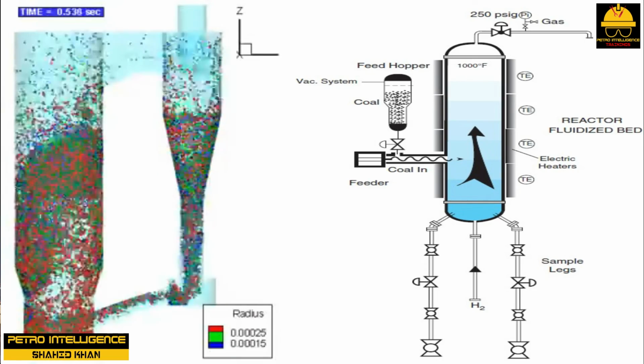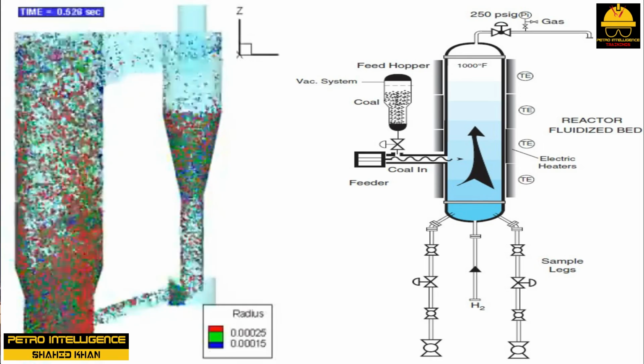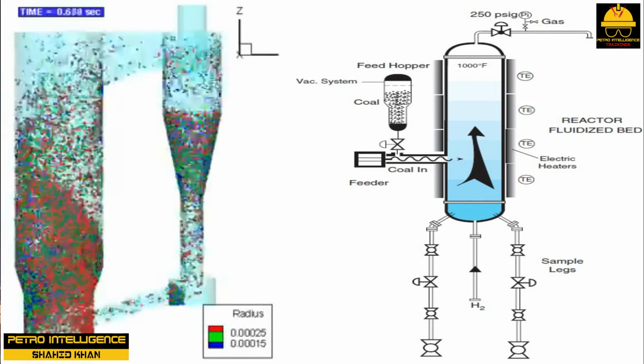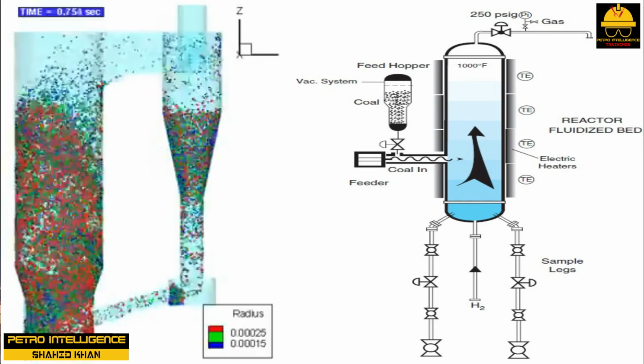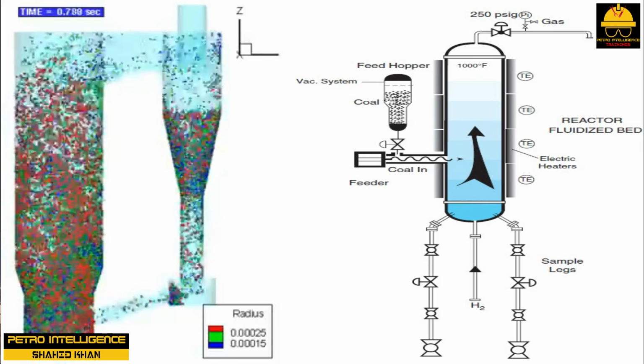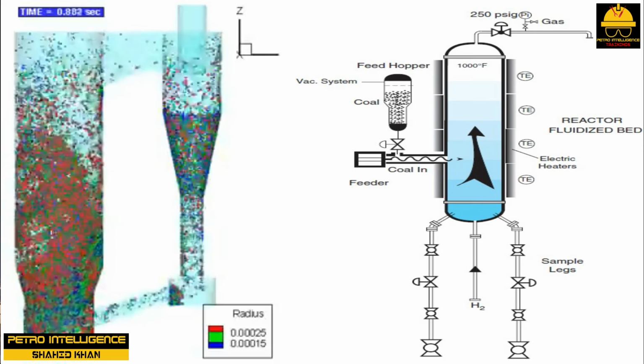Hydrogen gas inlet flows are mounted on the bottom of the reactor and must be controlled to keep from blowing the bed material over the top. A solids feeder is mounted a third of the way up the reactor. As the auger turns, coal is fed into the reactor. Methane gas is released during the run.